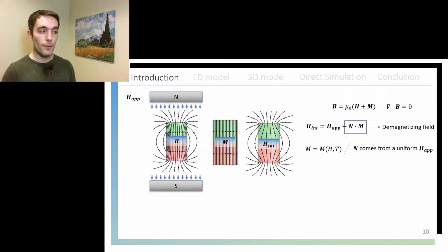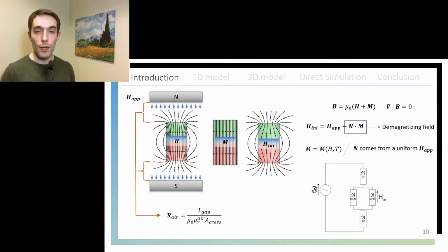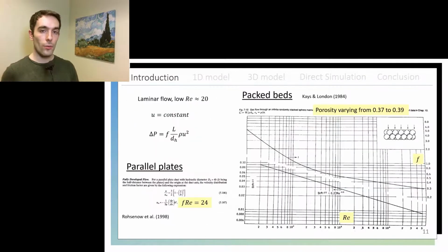This approximation comes from the case where this is exactly true, and that would be for ellipsoids of constant magnetization under a uniformly applied magnetic field. And there is another aspect of modeling the magnetic field, that the applied field is never uniform. That can be approximated as well by resolving a simplified magnetic circuit between the poles of the magnet. So we would calculate the reluctances of the materials that are between the poles, and then we would solve a magnetic circuit that is an analogous concept to the electrical circuit, so the effective magnetic field on the sample would be analogous to voltage.